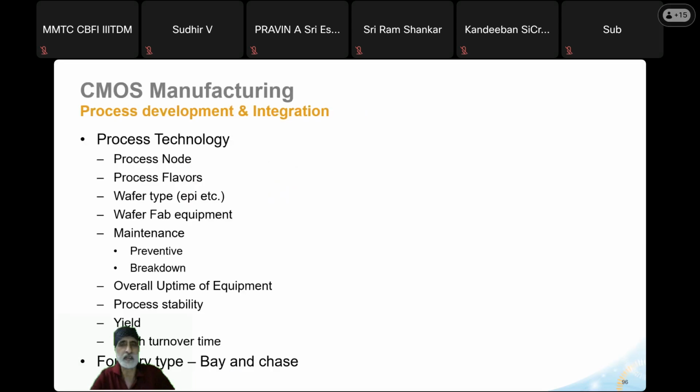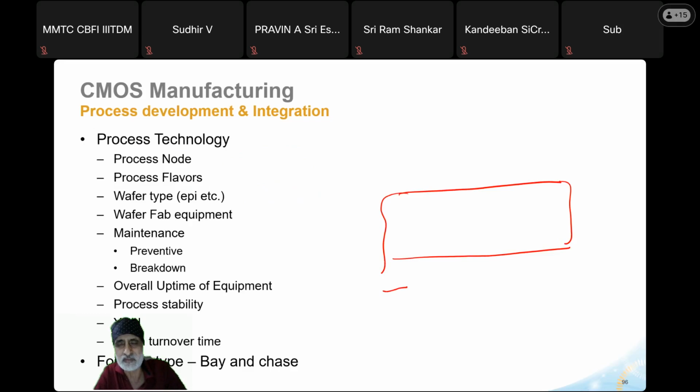The fabrication part is also known as a process, so we call it process technology. In brief, if I draw the sketch of a MOS device, which is a metal oxide semiconductor, this is a cross section, and we will start with P substrate wafers. Normally these are 12-inch wafers, around 825 micron thick. And on these, various layers are deposited on top of it.